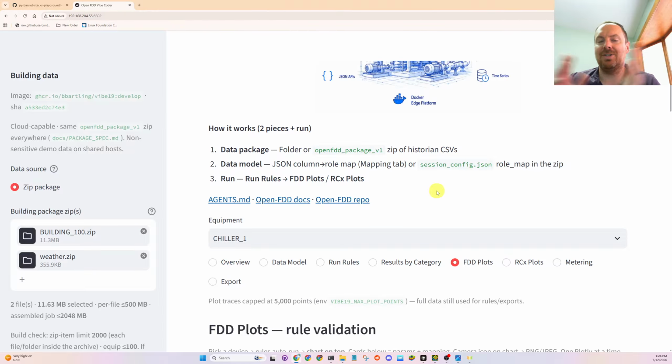And then also how well it performs on design day conditions. It would be nice if you had some design documentation. We don't know how big the chiller is, how many tons of cooling. I think it's an air cooled chiller. And then what would be the design inlet and outlet temperatures, and when it's running in design day conditions, which would be really hot, do you get that 10-degree delta across the chiller like you would?